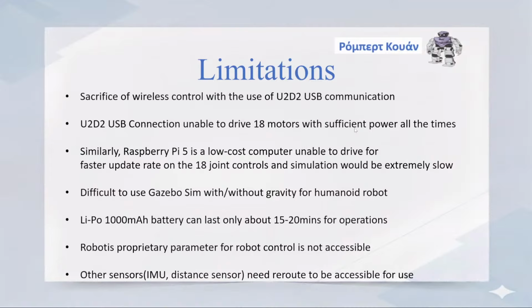And then, as I mentioned before, Gazebo really caused me a lot of trouble because I tried to play around with the different physics engines they had, Dart Sim, TPE, Bullet, but none of them really worked for me. And the robot actually came along with a battery, but I didn't use it in this experiment because, even after I fully charge it, it would only last 15 to 20 minutes for the operation. So it's very inconvenient. That's why I just plug into the power directly.